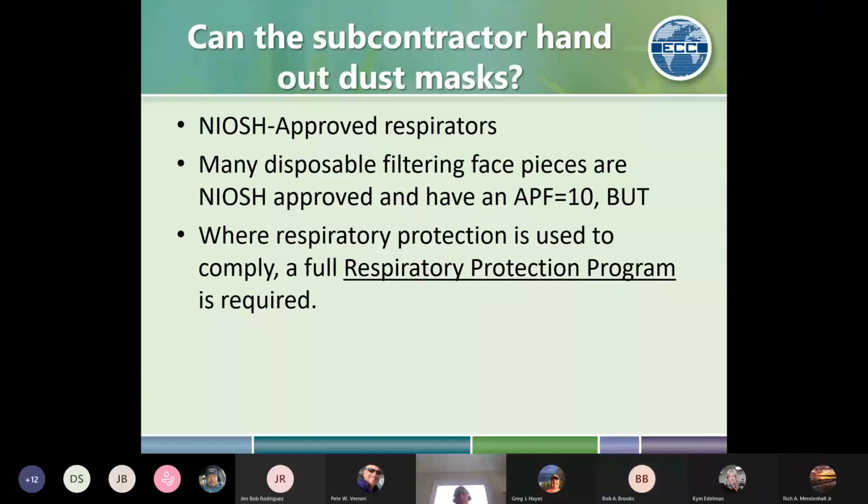And I think Galson now uses a different type of size selector, and it's actually disposable, which I've never actually used, but I know Ted Johnson has used it on some of his sites. It's actually much smaller and easier to use. So that would be a good choice, but it's probably still flow rate dependent. And if you get, like Kim said, all the equipment from Galson, they should have the flow rates set to what that selector needs, but just double check it.